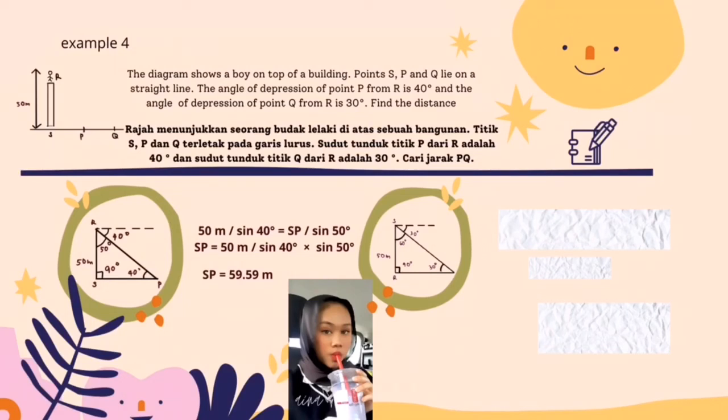Now that we have found the length of SP, we will be finding the length of SQ. To find the length of SQ, we can use the sine rule formula or the SOH formula. But right now, I'll be using the sine rule formula. We'll be substituting the values into the sine rule formula. 50 over sine 30 equals SQ over sine 60. After we calculate it, we can see that the length of SQ is 86.60 meters.